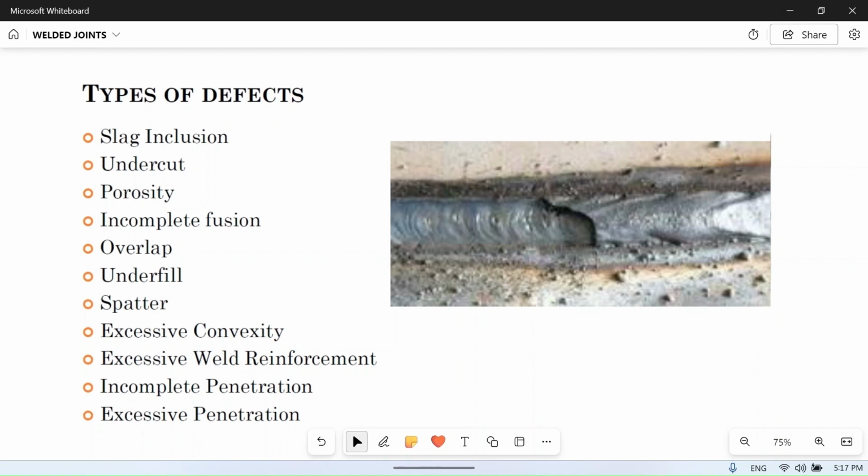As you know, when we are doing welding with two plates, we use filler material and sometimes we coat it with chemicals so that it can produce flux, to prevent oxygen, other gases and oxides from affecting the joint. This flux sometimes mixes with impurities and forms slag, which is lighter than the parent metal, so it floats on the molten metal.